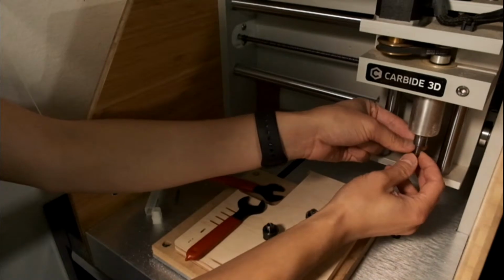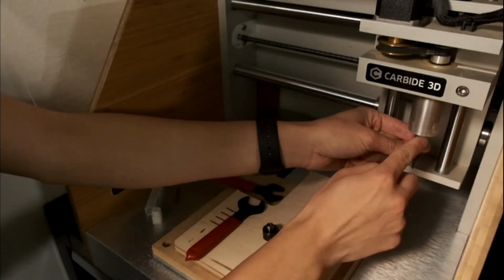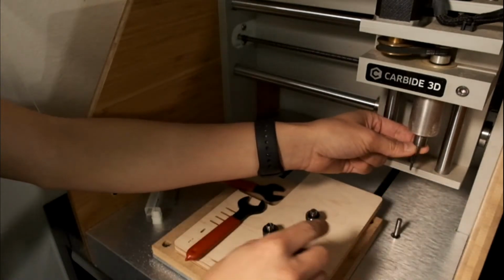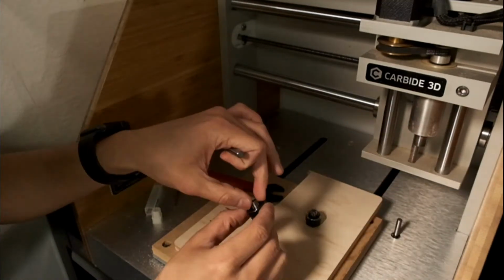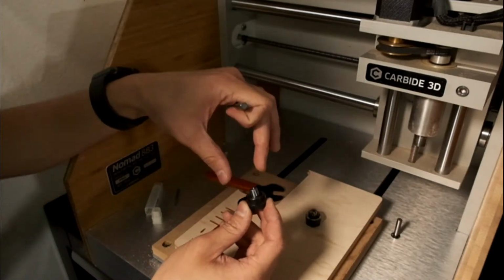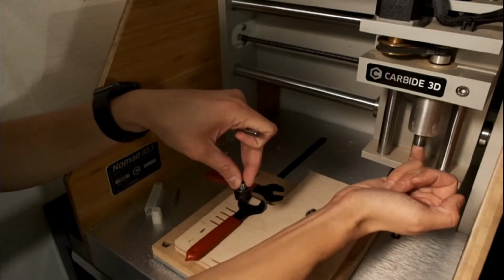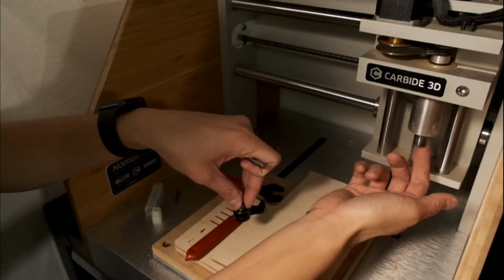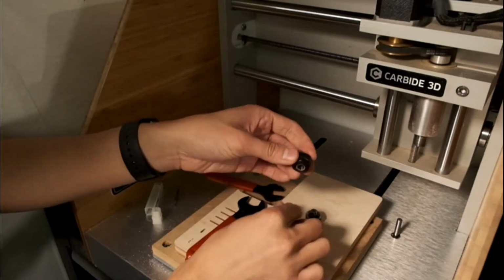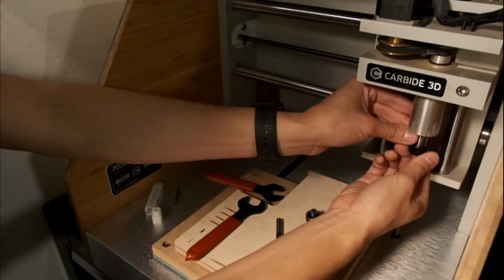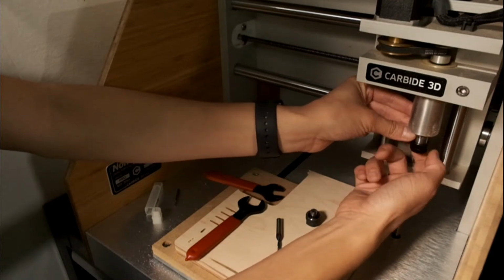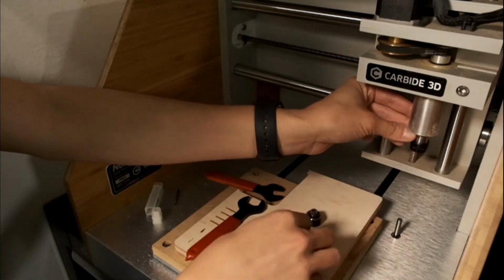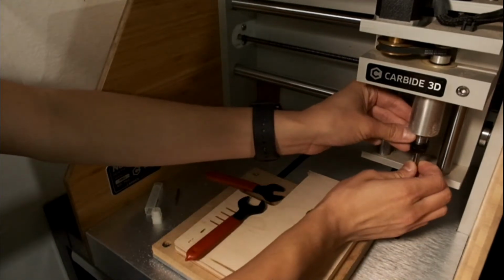And you never want to actually fully seat this against the taper in the back because the lower portion of the taper is what the collet aligns itself against. The upper drilled portion where the spindle is hollow, it's not really a great reference. So for the Nomad, I like to insert the end mill.